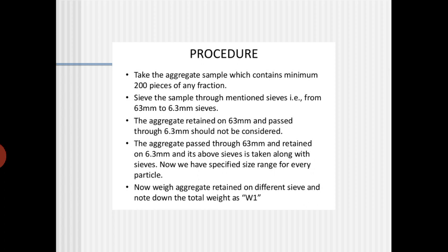Of course the crusher powder is very dangerous, and it will create respiratory problems when it goes into the human body. So based on the applicability, this crusher powder will be used, and less than 6.3 mm aggregates can be used for preparing the crusher powders.